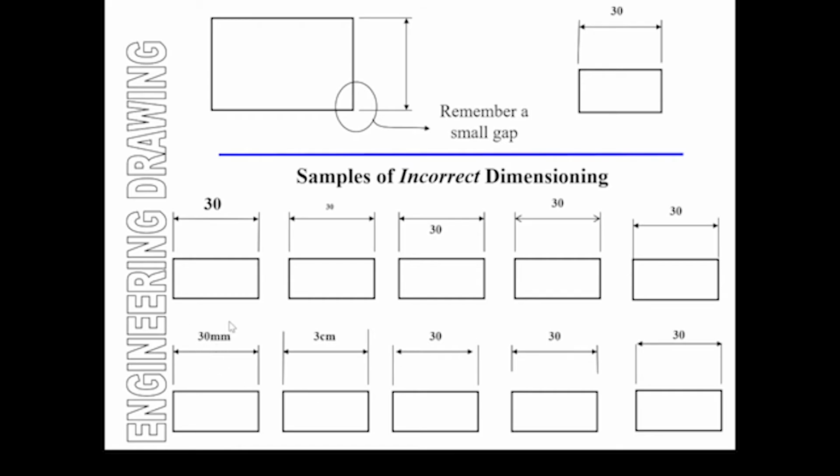Units, this is not necessarily incorrect in case you're dealing with a drawing where this is the only unit, or the only dimension which is in the metric system, then probably that's not wrong, you know. So we can talk about that one. Well, generally standard practices avoid units. If they're all millimeters, just have a little message in the title block that says all dimensions are in millimeters